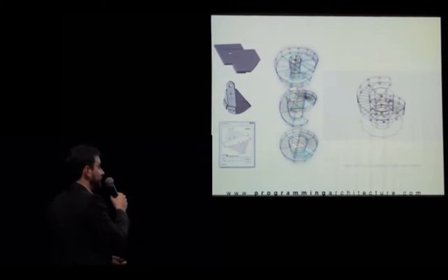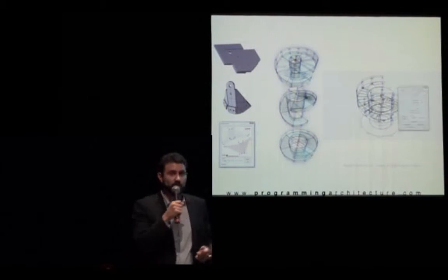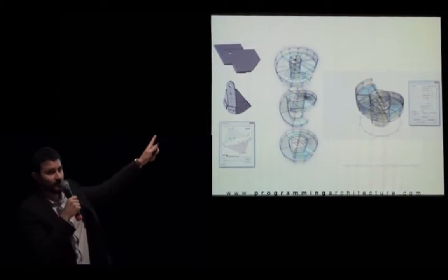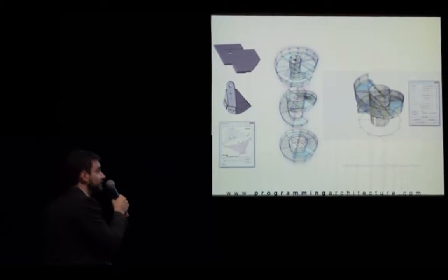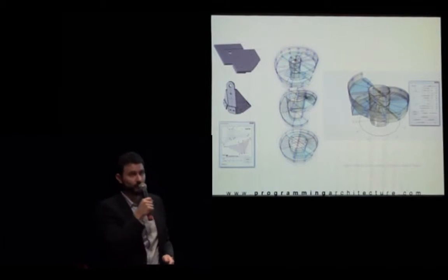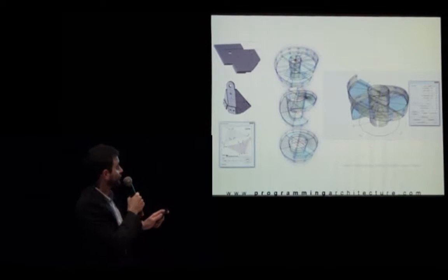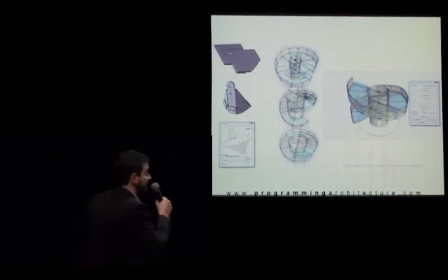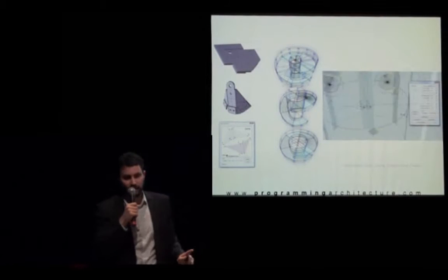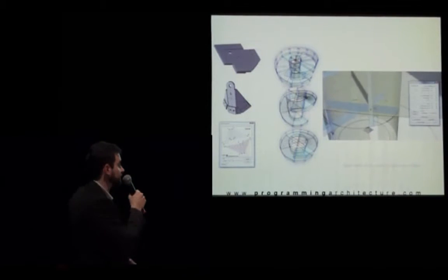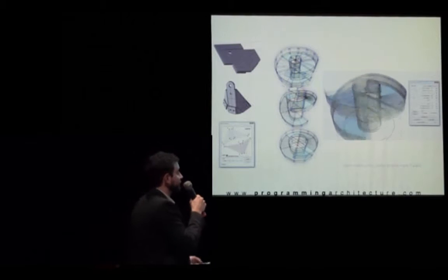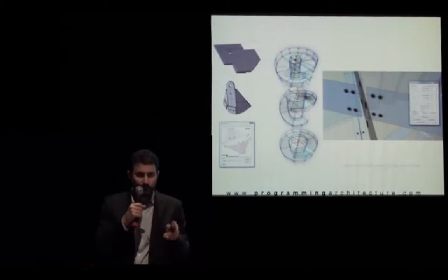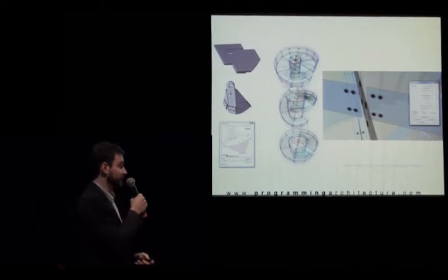So what I did was I parameterized the stairs, not only the geometry, but the statics as well, which means that what you see generated live here is a 30,000 structural member statical model. Once you define everything you need, you press one button and the model is prepared for static analysis. You don't need those 8 weeks anymore to build the model in the statical software from zero. And once it zooms in, you can maybe even see that there are many, many structural details. The statical model is very, very different from the geometrical model.